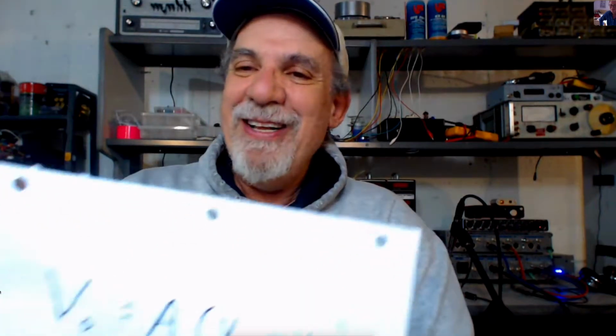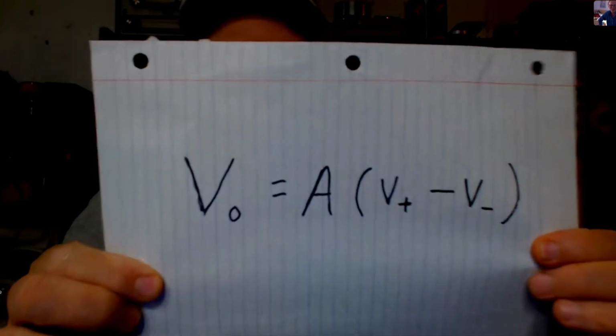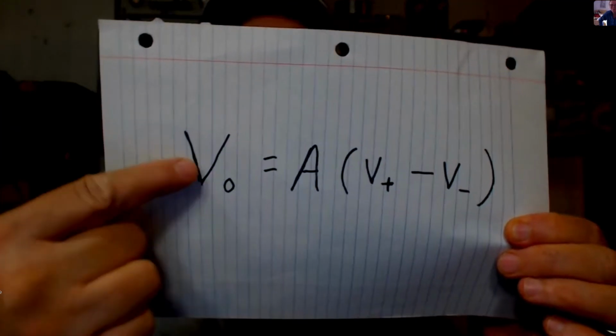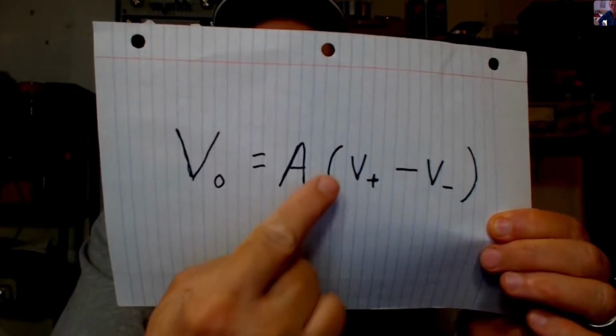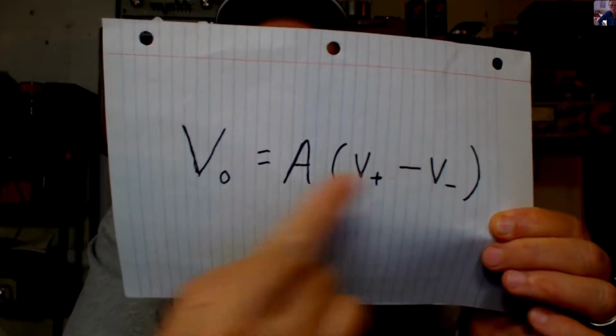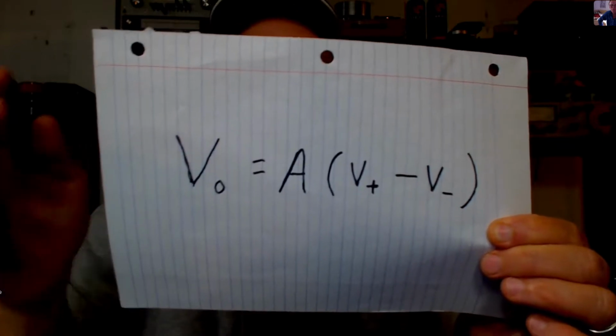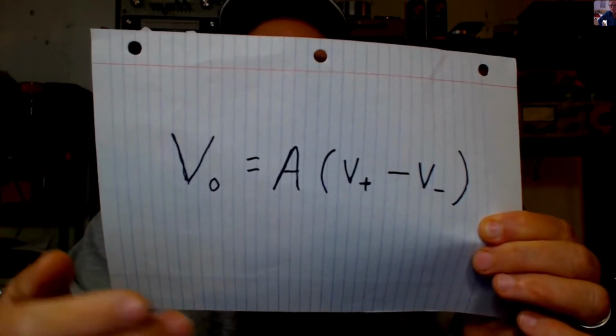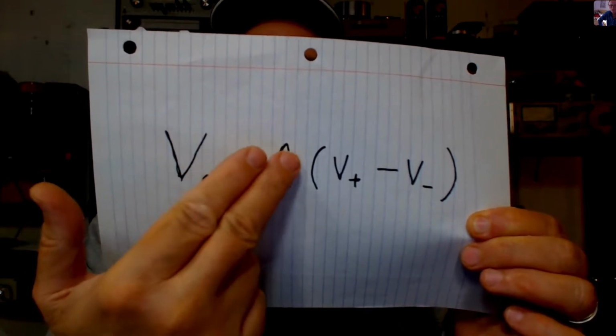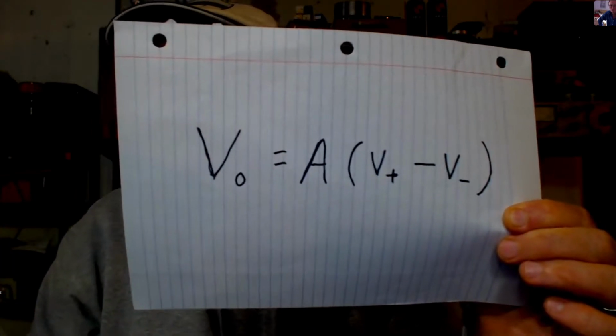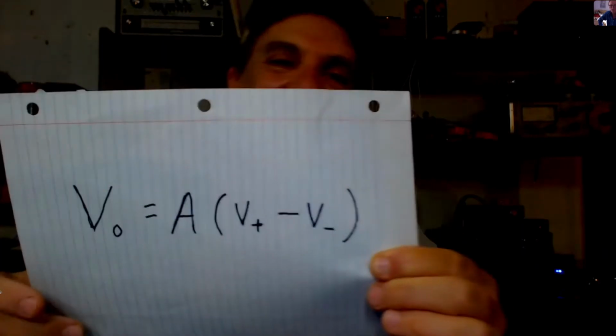That's the basis of op-amps. But an op-amp has one other interesting characteristic. I'll get another one of my famous drawings. This is what the output looks like. The output looks like some constant A times the difference between those two input voltages. And what makes something an operational amplifier generally is that A is very large. I mean, very, very large.